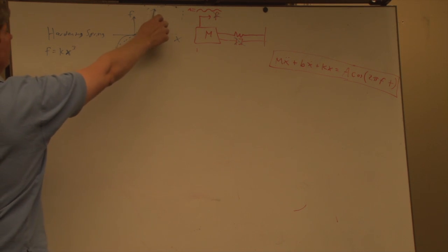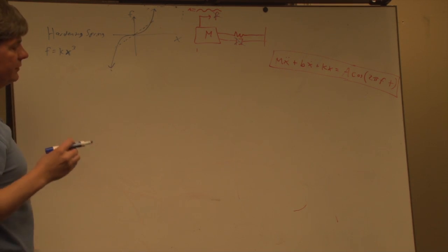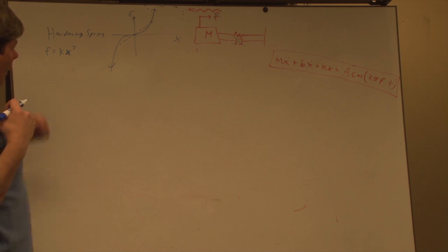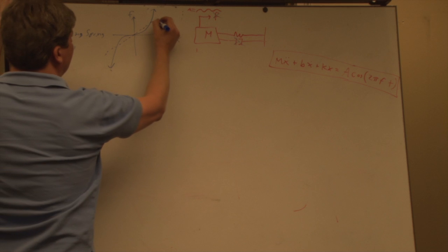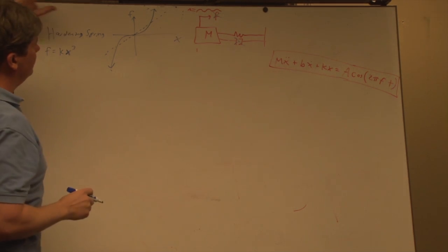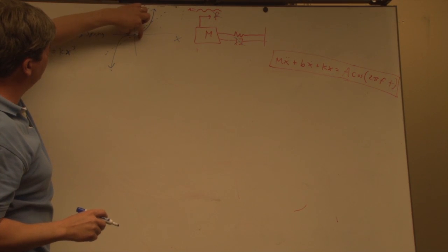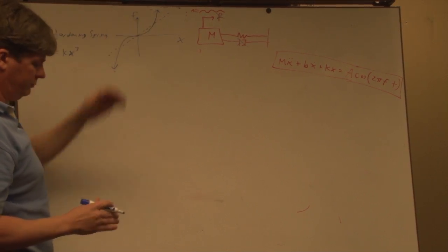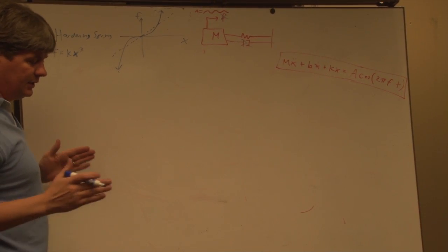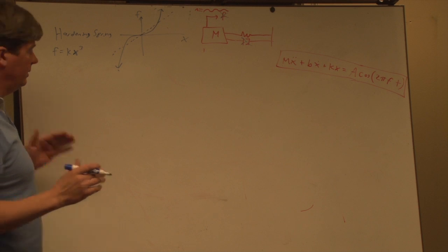And then at high amplitude, it gets stiffer and stiffer. If you were to linearize it about low frequency, low amplitude, that would be a real loose spring, which would mean that the resonant frequency of that system is really low.